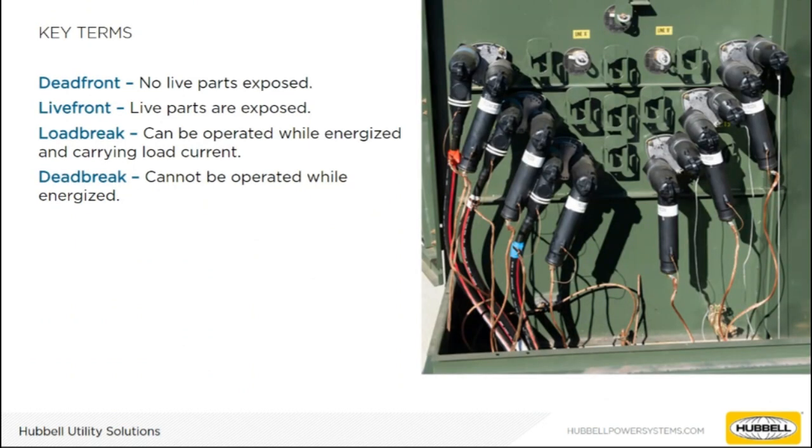All cable accessories fall under two main categories: dead front and live front. Equipment is considered to be dead front when the operator is not exposed to any high voltage parts. To maintain dead front criteria, all connections must be protected with rubber and all voltage carrying parts cannot be exposed. Live front means that high voltage parts will be bare and poses as a safety hazard. For this reason, utilities are transitioning more towards dead front equipment when available. All Hubble underground separable connector products are dead front.